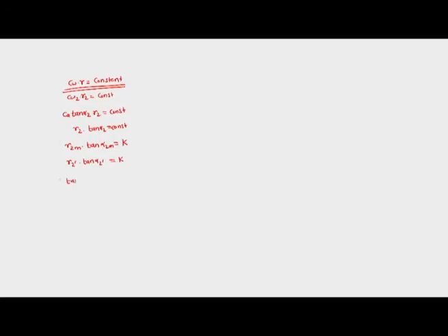So tan alpha 2 dash is equal to R2m divided by R2 dash into tan of alpha 2m. So we can find tan alpha 2 at some other height when we know the radius of that height and tan alpha 2m at the mid blade height. This is how we can utilize the concept of free vortex theory to translate the velocity triangle from one height to another.